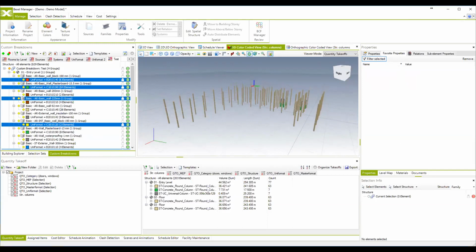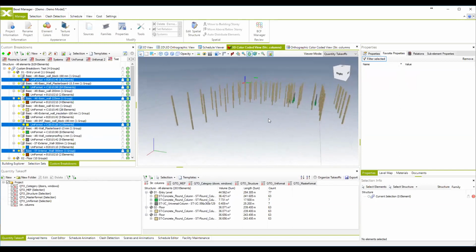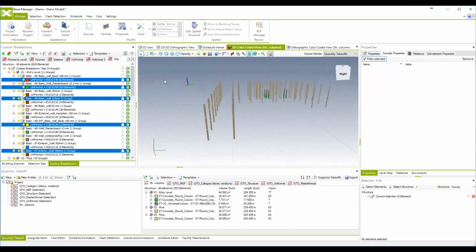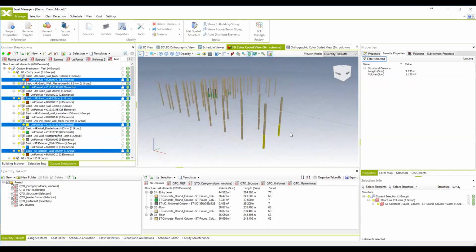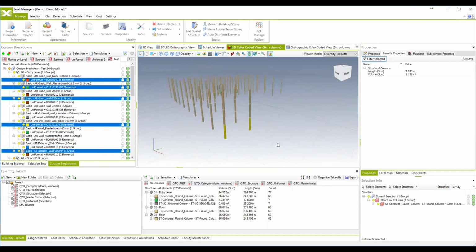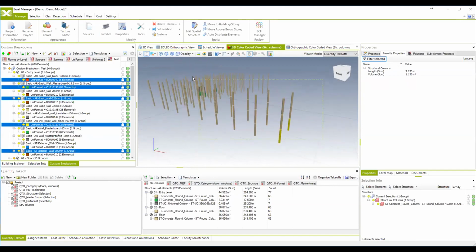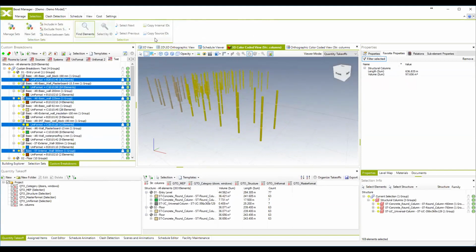So this is really a great tool for quantification. And when I mentioned the IDs of the elements, a tip for selecting the elements, and selecting the same elements in the authoring tool, is actually using their unique IDs. So when you select any of the elements in the BEXEL Manager model, you can use this tool here, selection, copy source ID, and you see the software automatically copies the source IDs of these elements.